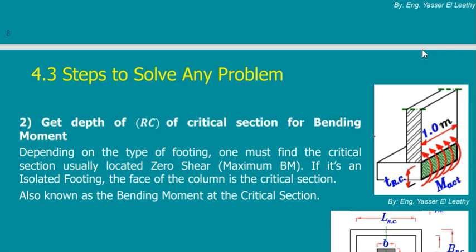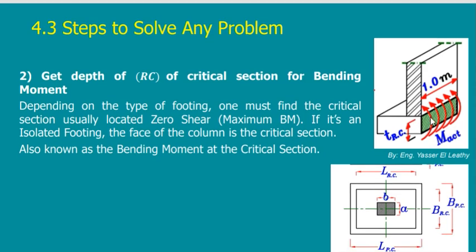If you have both moments equal, then you can design only one. How can you have both moments equal? If I have equal cantilever from both sides. So this you can take into consideration. Now, this is the shape of the moment.